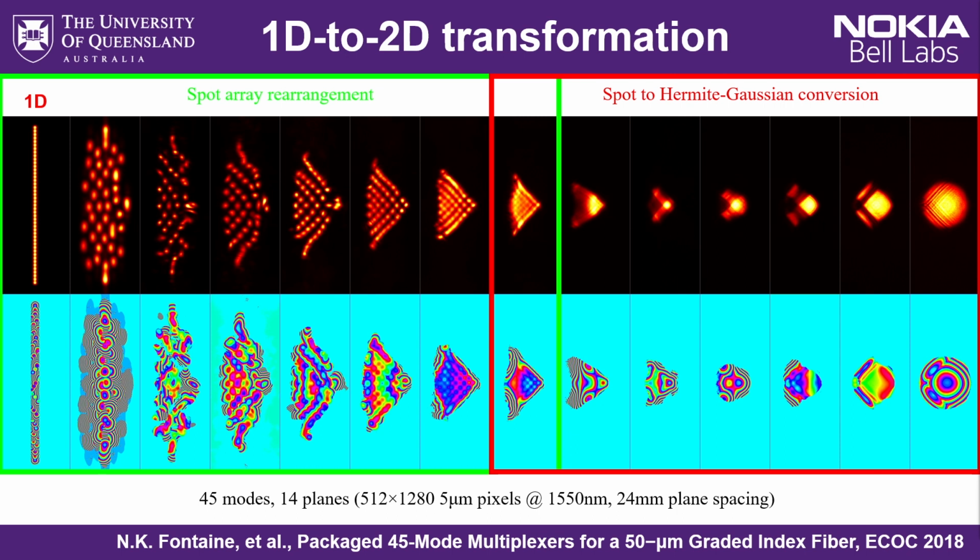So it's a bit like taking a 2D image and then rearranging the image such that all the pixels are in a single line. It's got all the same information in it, but you've sliced and stacked it up into a single dimension. That can be useful for interfacing with things like waveguide arrays or photonic integrated circuits, but it's also useful for analyzing or manipulating 3D beams using 2D surfaces, and I'll discuss that in a bit.